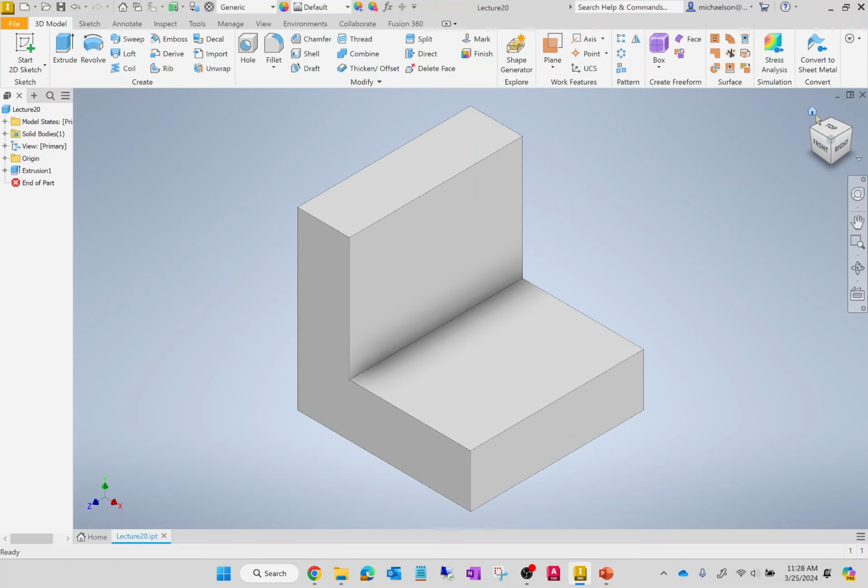The other thing that I'll mention is the little navigation wheel, okay? Now, down here on this little toolbar on the right, there's a bunch of options. What I want to click is this top one, this full navigation wheel, okay? Now, this is what the navigation wheel looks like. You can always close it by hitting the top right corner, but you've got a lot of power here in terms of affecting your view. The way that it works is that you click and hold one of these buttons, and then moving the mouse will respond accordingly.